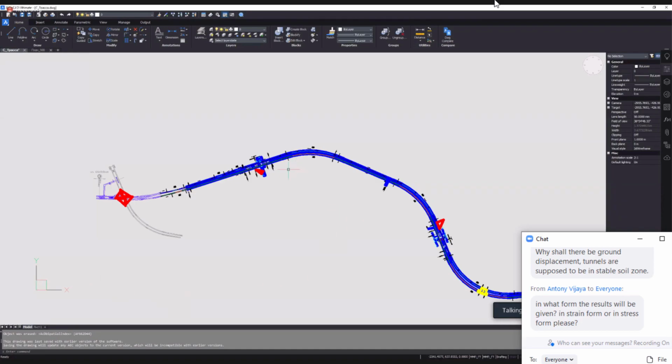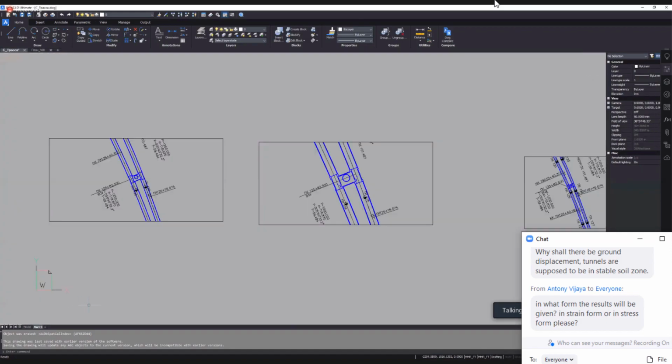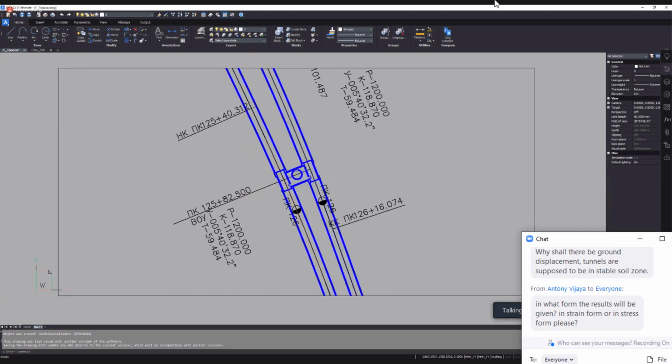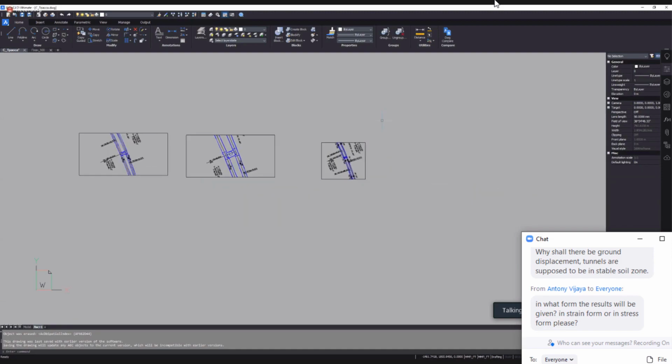For the first stage, we work on the wall in the soil, meaning that when they do excavation to a depth of about 25-30 meters, they are interested in the soil pressure on the construction. For that we use different kinds of technology, mainly FBG, and we install fiber optics on every point where needed, and then give information to the central office in Minsk.